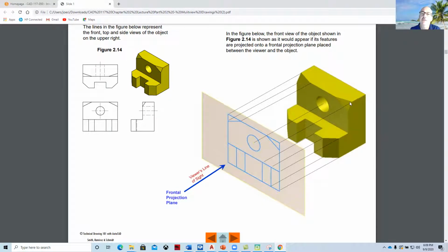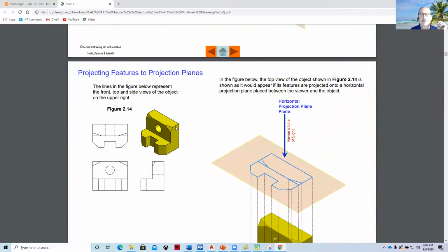These triangular shaped oblique surfaces are called oblique because they're not perpendicular to the line of sight. They're not flat, they're at an angle. And so the circle is perpendicular, so it appears round. If it was at an oblique angle, it would appear like an ellipse. And so these are not true size as we get into creating these shapes on two-dimensional paper.